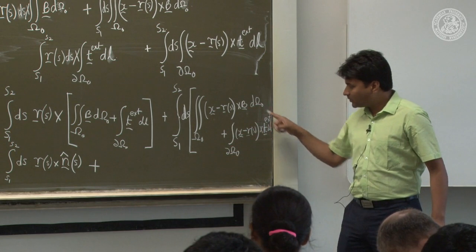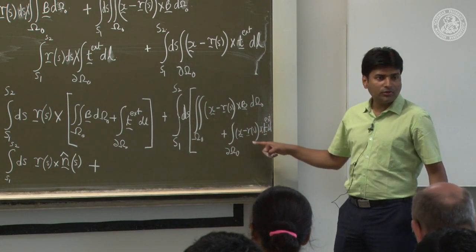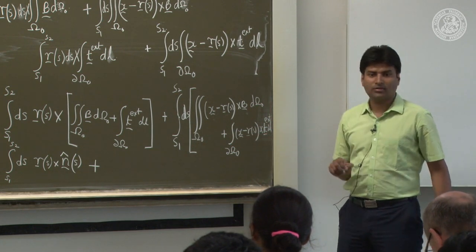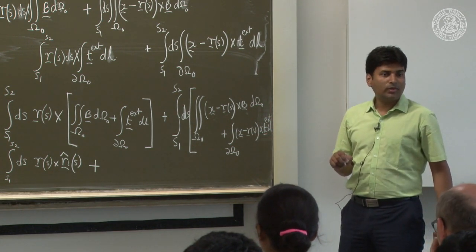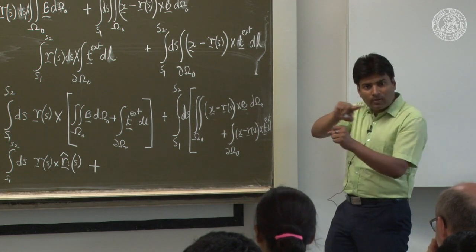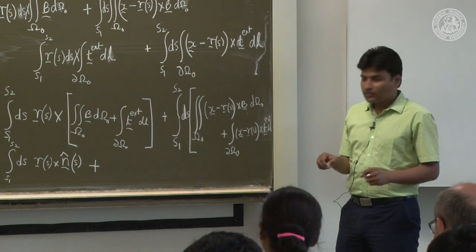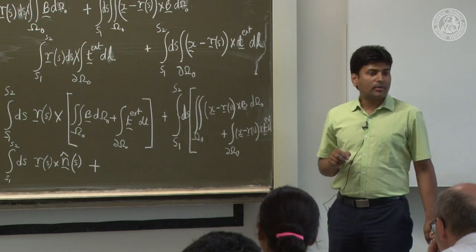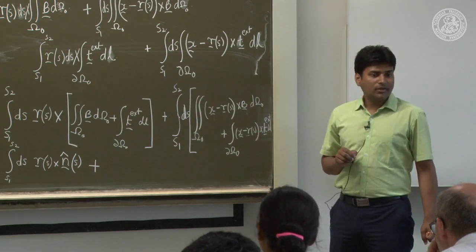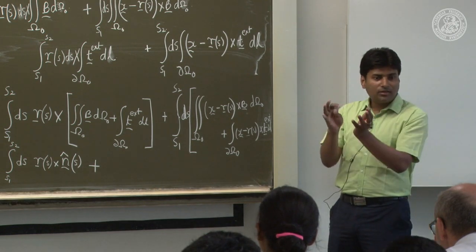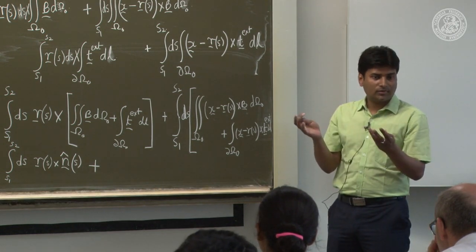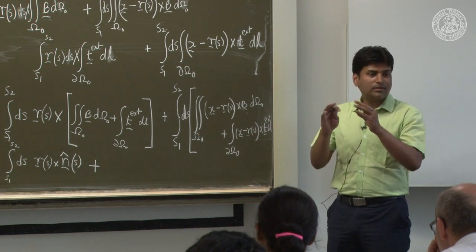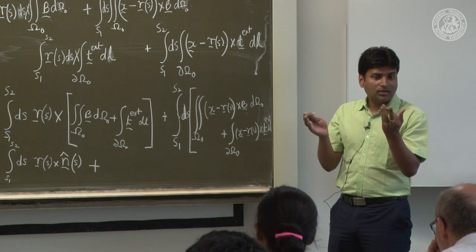Similarly, this term is the couple due to the lateral traction and again about the center line. So in your beam mechanics, when you see you have distributed couple acting along the beam, that comes because of these two terms. If you have a gravitational force, for example, the distribution is such that the couple due to it is 0, but you could have the distribution of body force. If it is not symmetrical, it could create a couple.